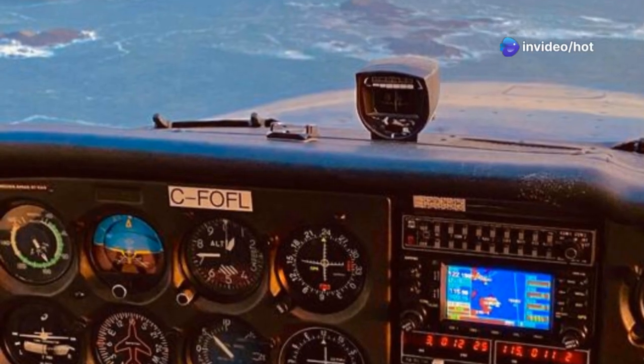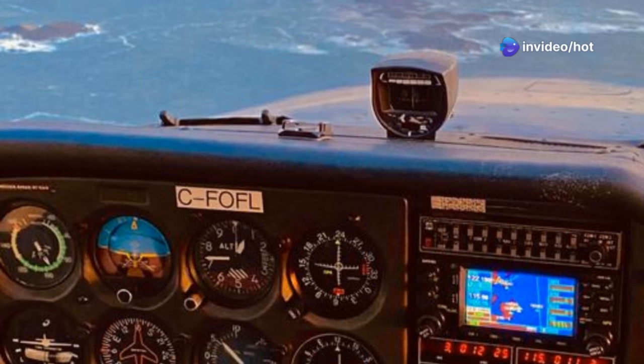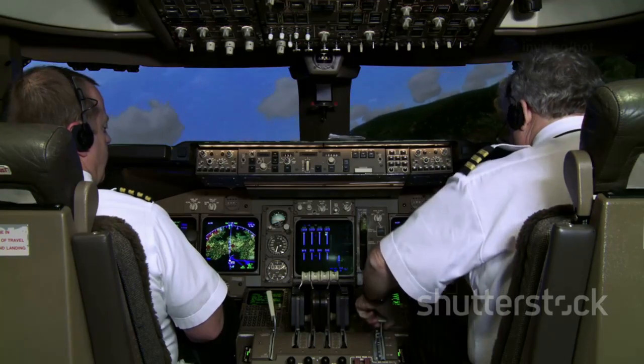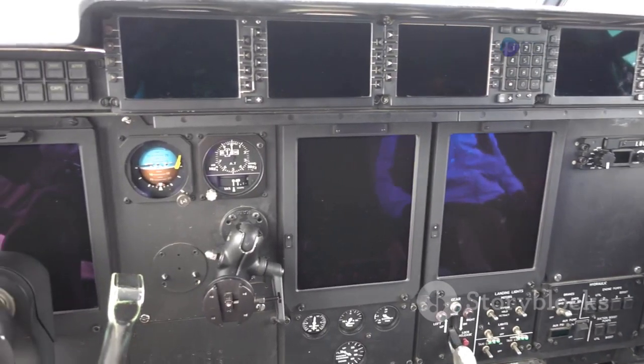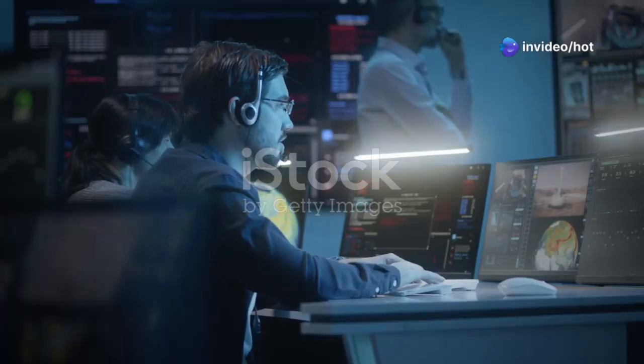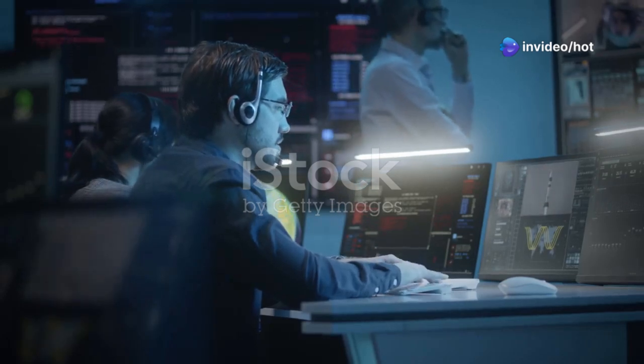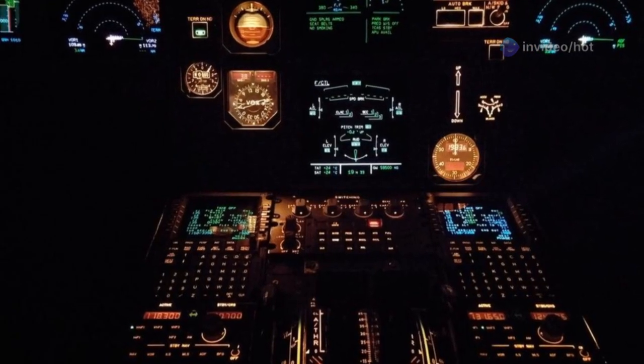The semicircular rule is widely adopted, especially for IFR en route. This provides a good degree of international harmonization. Most of the world uses east odd, west even for IFR. This is for flights above the transition altitude or level. This consistency simplifies international flight operations significantly, however differences can be found.